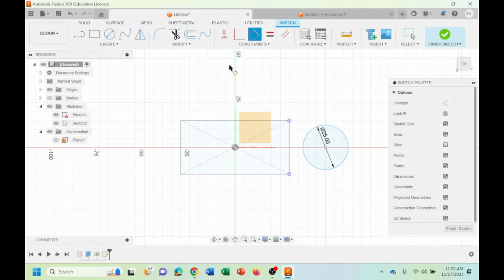So I'm coming here, the tangent, this with this one. It still is not constrained. It is still blue and it is a pencil. We already know that. So now let's use the horizontal vertical constraint and make this point vertical to this point. As you could see, now it is fully constrained.